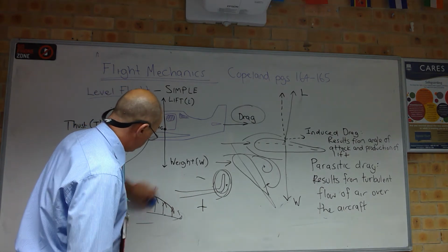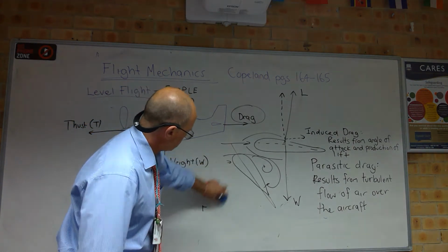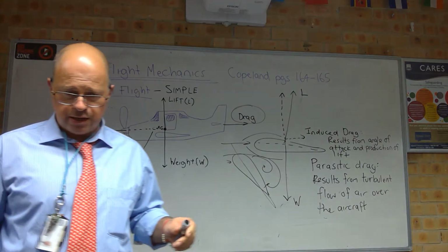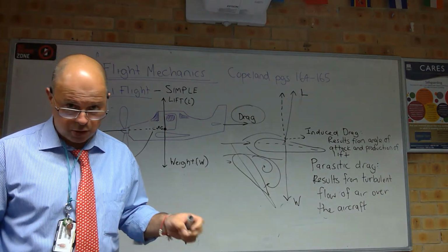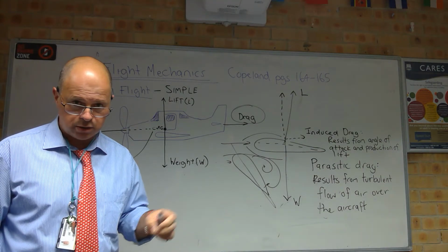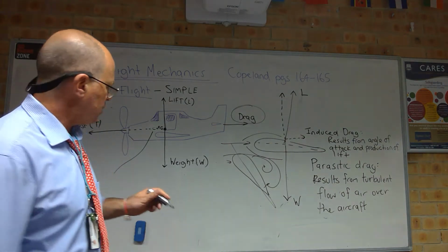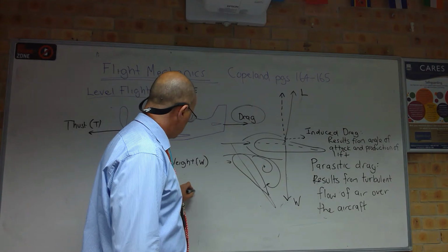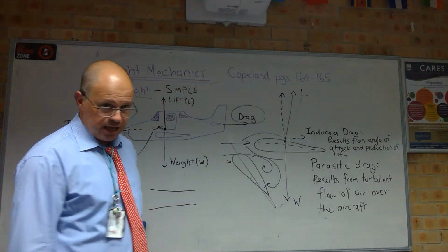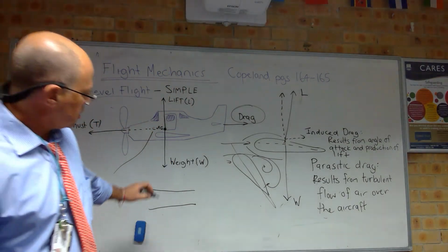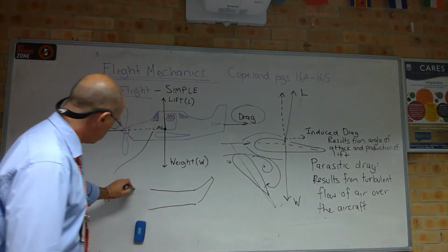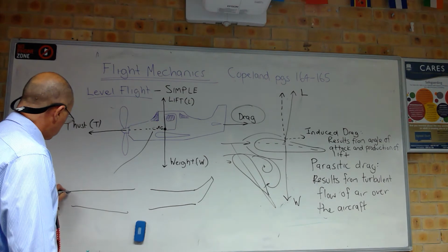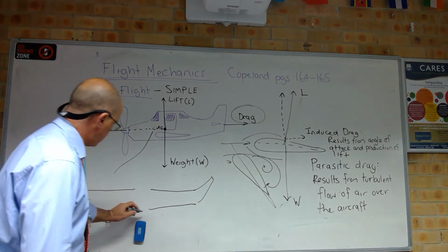Now the wingtip winglets are very common, and they certainly assist in both the climb and the descent most, in stopping those vortexes from happening. Some aircraft, the newer Dreamliners and stuff, if you look at the wing from above, it doesn't have a winglet, but the wing at the tip, at the end of the wing, sweeps back. So if you're looking at the aircraft from the top, its wings sweep back like that.